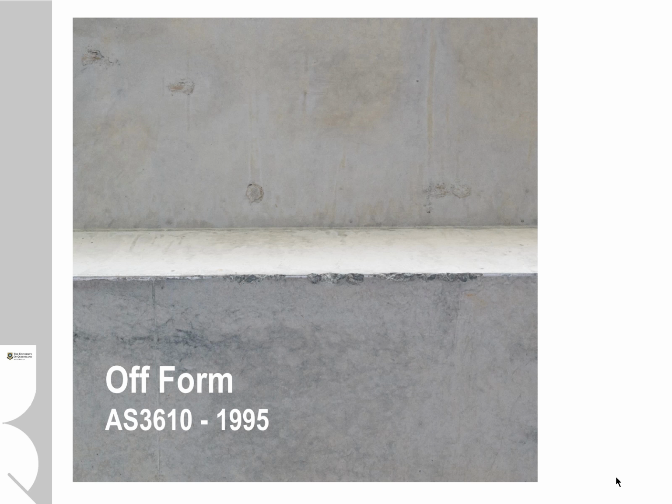Now, it's important because to simply specify the highest quality concrete finish all the time will make our construction very expensive. The standard AS 3610 will define the surface types in different situations, so concrete that is not meant to be seen as a decorative finish right up to the highest quality exposed decorative concrete.